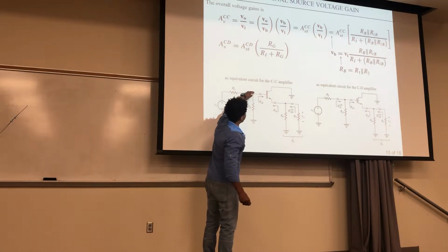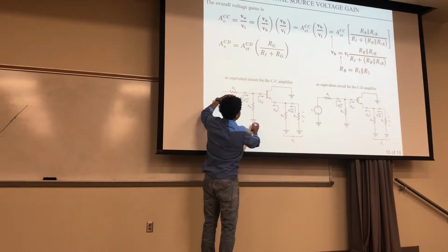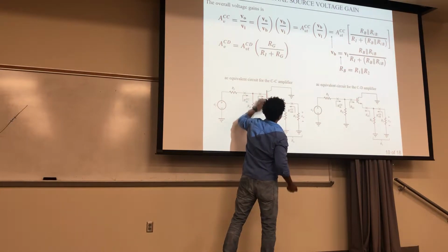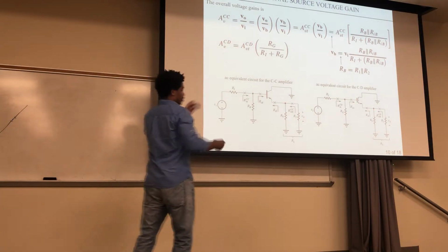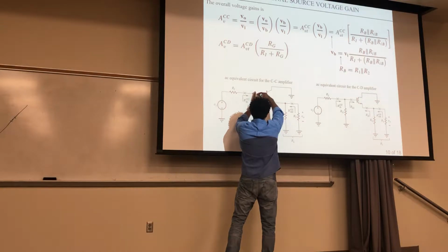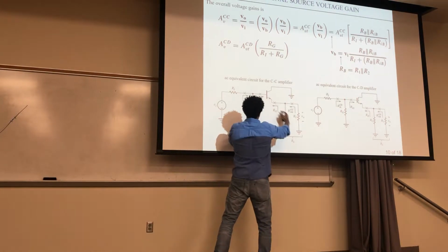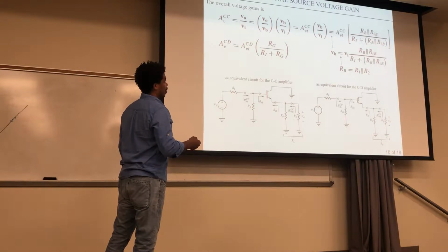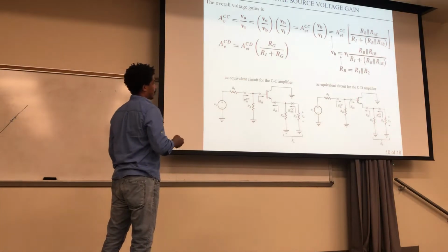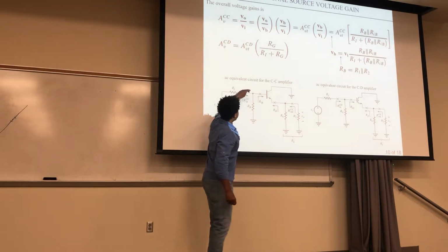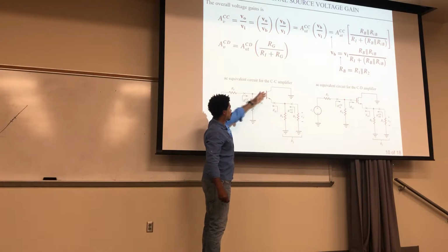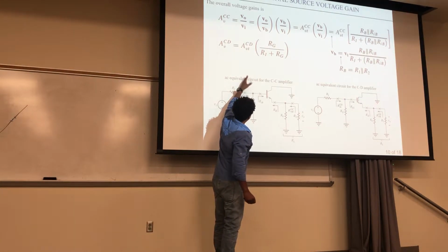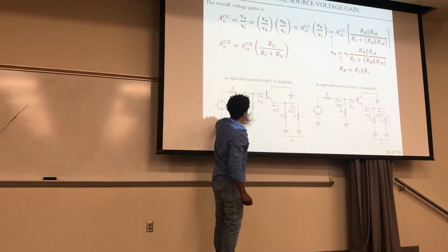So for VB, right here, that's just these two in parallel, right? And divided by those in parallel in this RIB. Wait, I'm sorry. It's these in parallel right here on the numerator, and that plus those in parallel on the denominator for the voltage gain. And this right here, this RIB, that was the R1, R2 when you're looking at your 4 resistor network connected to your amplifier. Because remember, this network is a small signal model. Okay, so that's why you don't see any capacitors there. And so this RIB, it took that R2 and R1, they folded them over, and so they're in parallel with that.